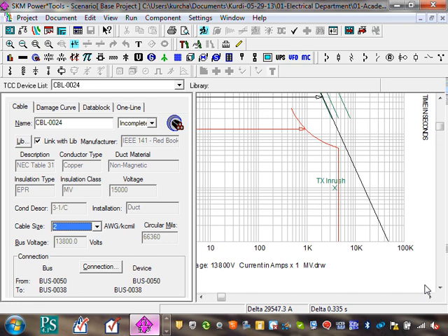So they're using 1,000 volt as the limit. When you go over 1,000 volt, you have a special requirement for equipment, and for 1,000 volt or under, a different requirement. They're not going to change the THHN into 1,000 volt, but there will be a lot of conductors that will have 1,000 volt insulation.